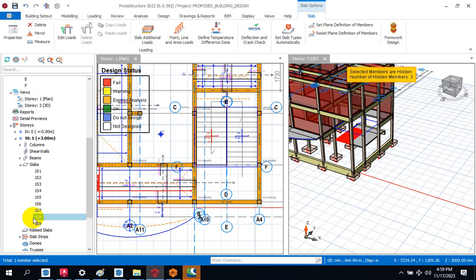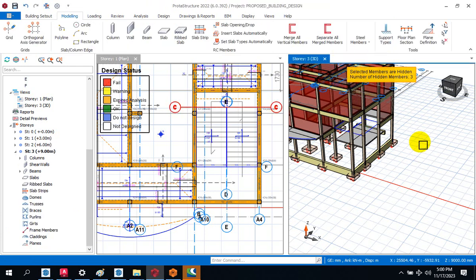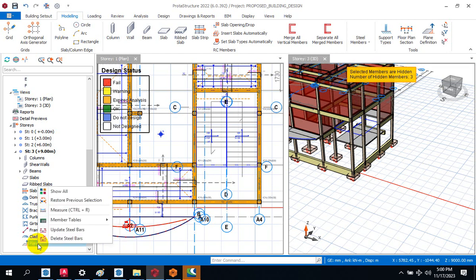Okay, yeah, sure. So that's the training. Then from the AutoCAD you can import it into the software. It's really much easier. You propose your position of columns, your position of reinforced concrete wall, and anything else you can on the AutoCAD. Then you do the importing. Your layers, like the column, should be on column only.